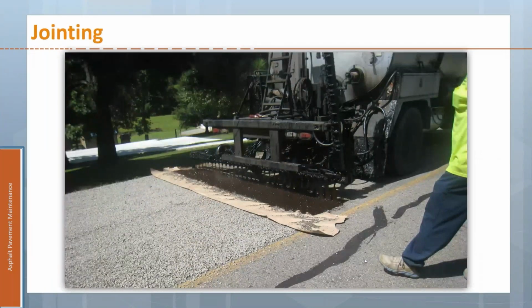Now, at the end of the day, you need to quit, and this is a pretty continuous process, so it's hard to start and stop, but essentially you'll turn off the spray bar and you'll drop those last bits of aggregate, but you've got a little bit of a messy ending there. So the next day, you need to come in and be able to pick up where you left off, and you don't want to see that intersection that looks kind of yucky.